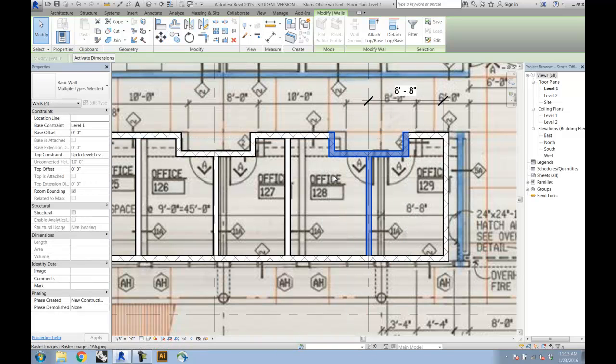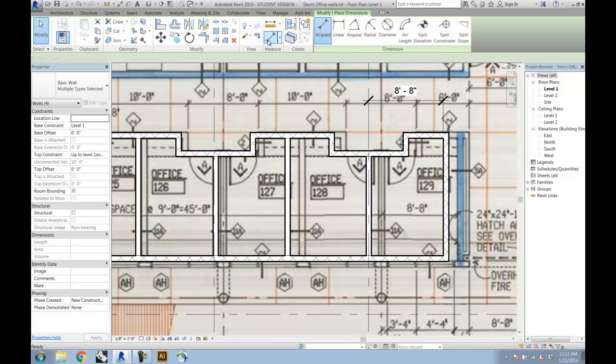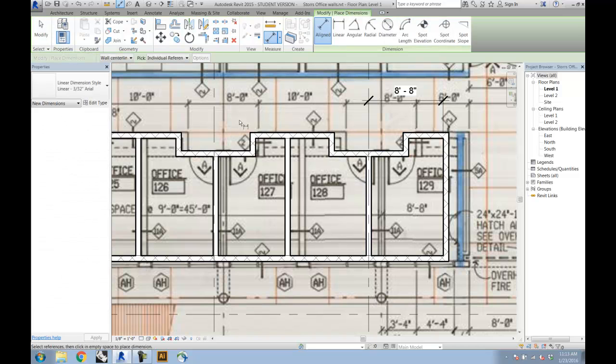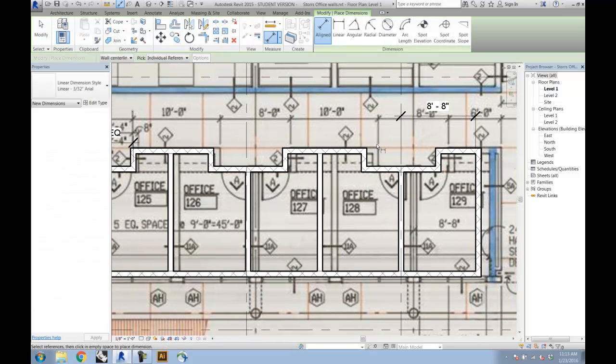It's going to move all the walls, all these objects further out in order to get this one centered. Those sorts of techniques you're going to want to pay careful attention to, and you're going to want to use, because you're going to be using them really often. So I'll just go down the line, repeating the same move. Again, hitting the Measure button, selecting the grid line, the center line between the offices, and then the next grid line. You can see how these are off. I click one more time to finish that.